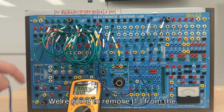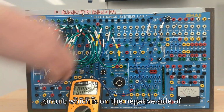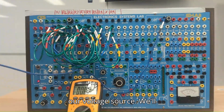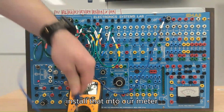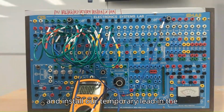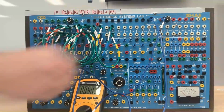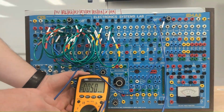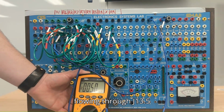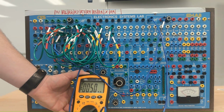We're going to remove J13 from the circuit, which is on the negative side of our voltage source. We'll install that into our meter and install our temporary lead in the spot where we took out J13. The current we're measuring flowing through J13, 0.5 milliamps.